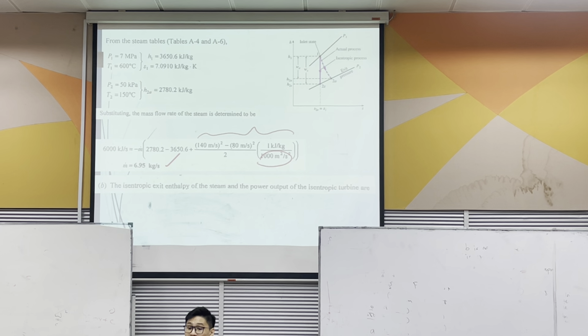Okay, then you need to calculate the isentropic efficiency. What we mentioned just now, this H2 that you found is H2A, right? Which means we need H2S in order to find the isentropic efficiency, because that's the equation. So now the question here is how to find H2S.